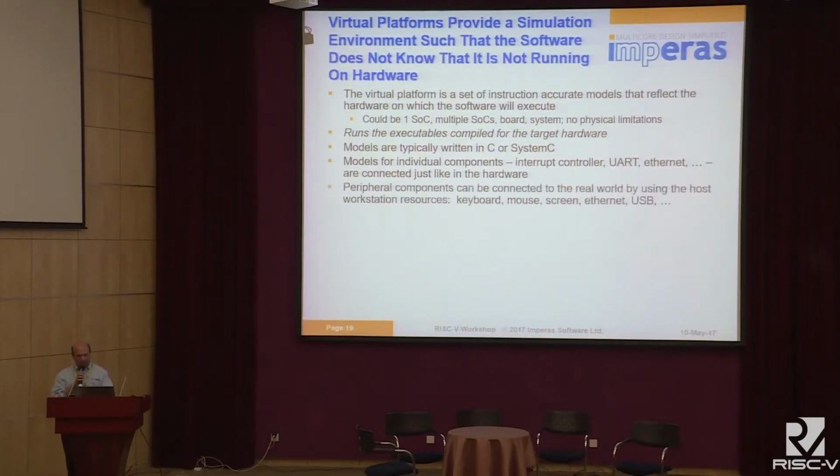So again, it's running the executables compiled for the target hardware. It's using the same tool chain that you would use for your hardware, but now it's running in a simulation. These models are typically written in C or SystemC. The models for the individual components, like an interrupt controller, UART, Ethernet, are connected just like in the hardware. These peripheral components can be connected to the real world. So you could actually use Ethernet and go out through the host PC Ethernet and onto the internet.